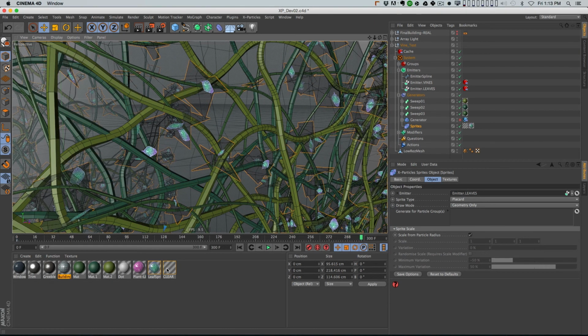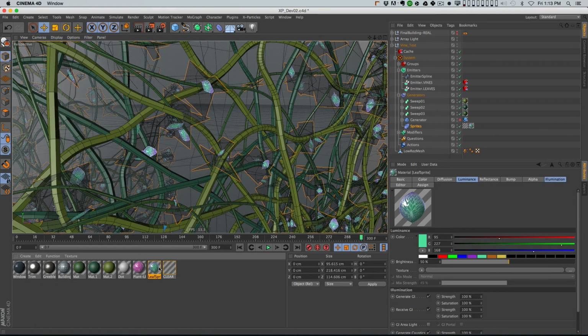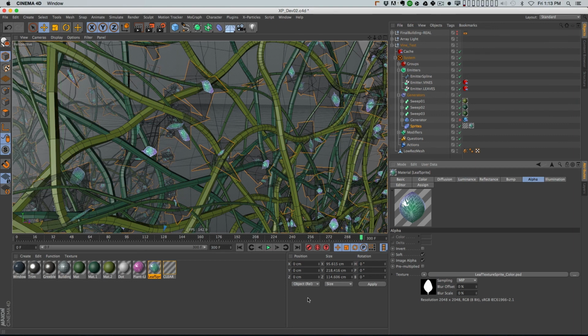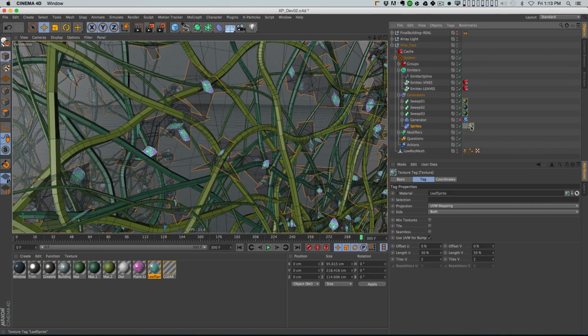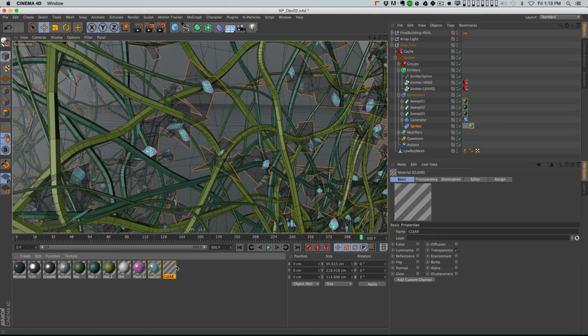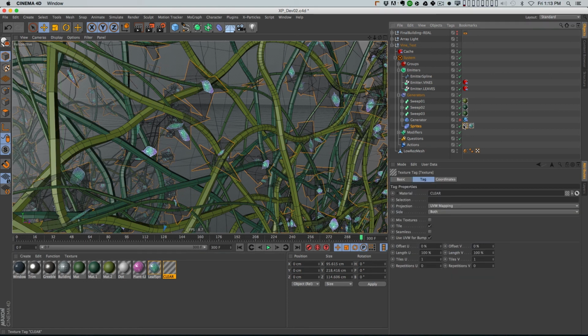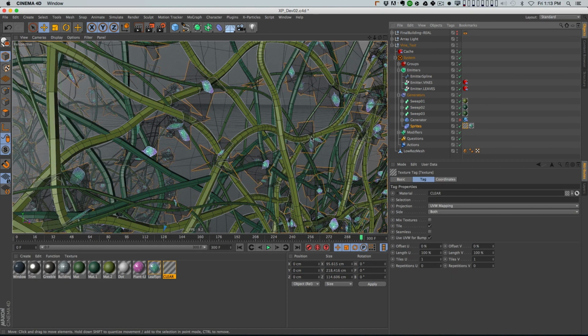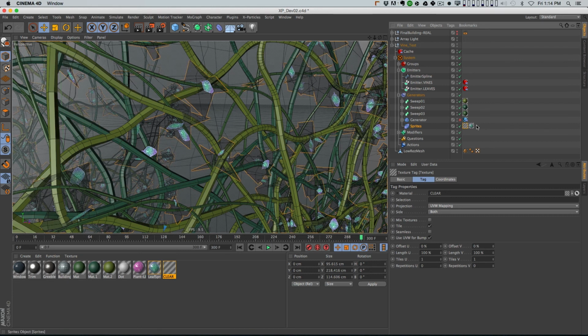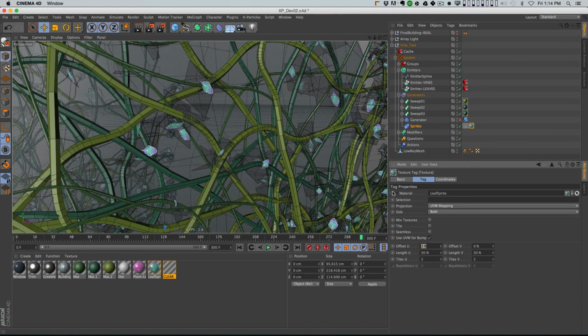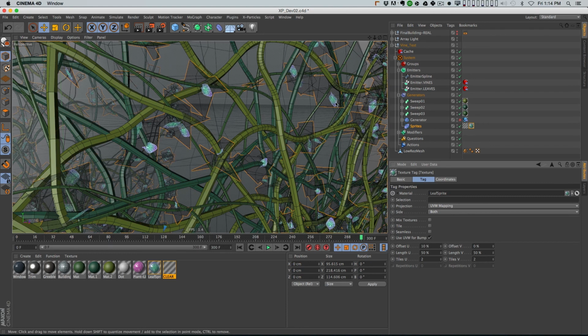Okay, I made a copy of my leaf material here, and I added an alpha channel to it that I just quickly made in Photoshop. What I did was I first put one material that has nothing in it but transparency to clear out and make this placard invisible. And then I put my leaf texture on it, and I set it to tile twice. And I probably need to play with the offset a little bit here so that we can get the leaf right in the middle.